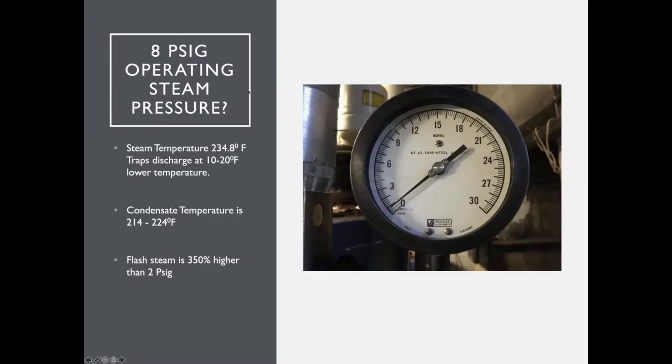This job we were looking at was operating at 8 psi steam pressure. So the steam temperature was about 234 degrees, and steam traps will discharge anywhere from 10 to 20 degrees lower. So they had condensate at 214 to 224 degrees. Well, at atmospheric pressure, it's going to flash the steam and boil. So if you're running at 8 psi, you're going to have 350% higher flash steam than you are at 2 psi. So all that is going to be wasted, and you're going to destroy the boiler relatively quickly.